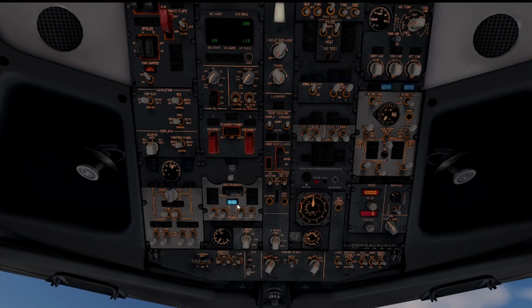So when we have disconnected from the APU gen, we can turn our APU off. It is a far up position of the APU power switch. I'm then gonna turn engine bleeds 1, 2 on, and APU bleed can come off. Now, when your engines have started, you can go ahead and you can turn on the air conditioning so they get air back in the cabin. Then you'll go ahead and put your left back to auto, right back to auto, and isolation valve to auto.